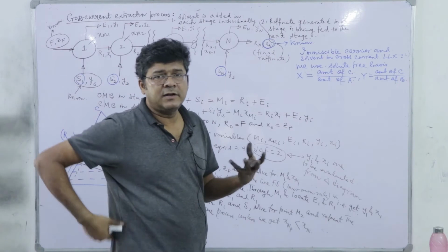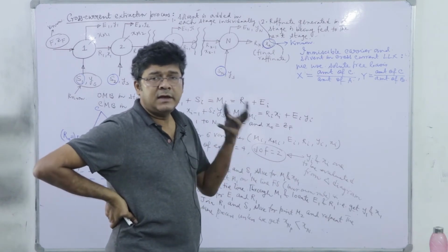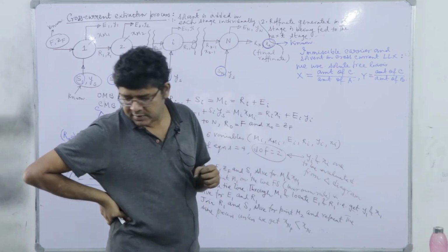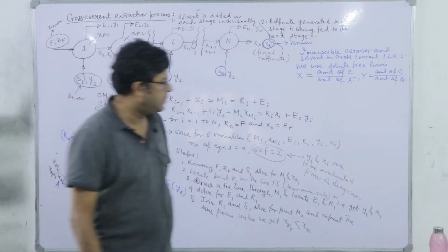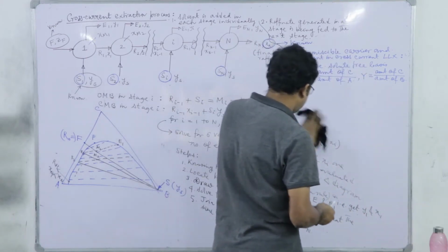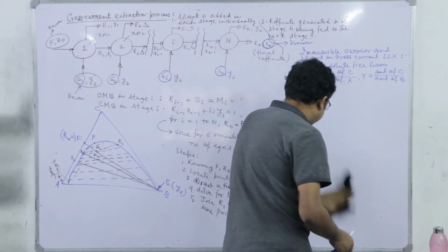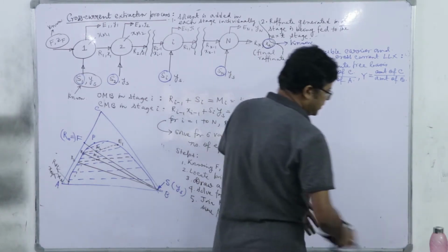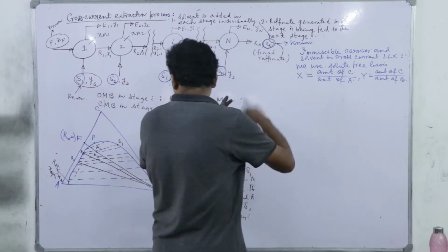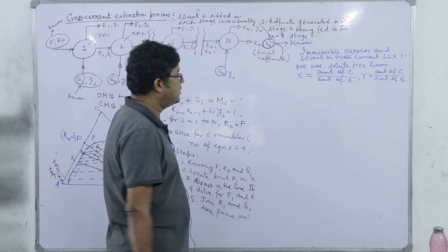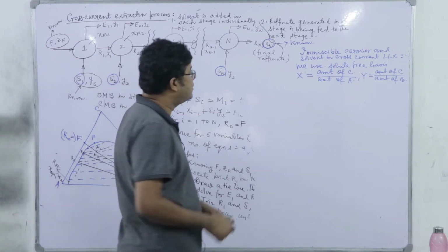In the extract it will be B and C only, in the raffinate it is A and C only, because A and B are immiscible. So under this situation you see how to go for this calculation of the number of stages. It is much easier compared to the previous one, right? Here the simple capital Y versus capital X space and the calculation in the respective space is sufficient.